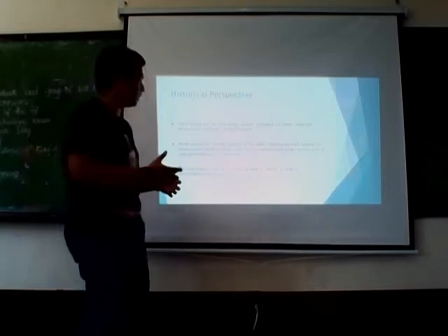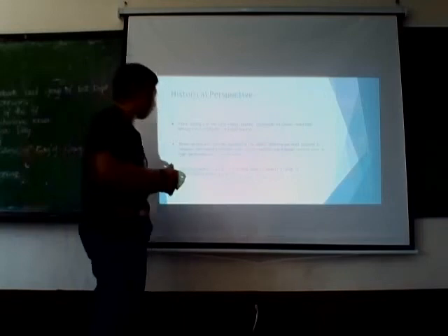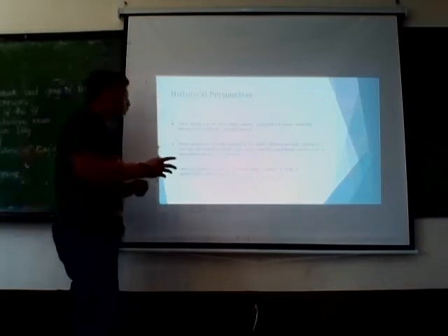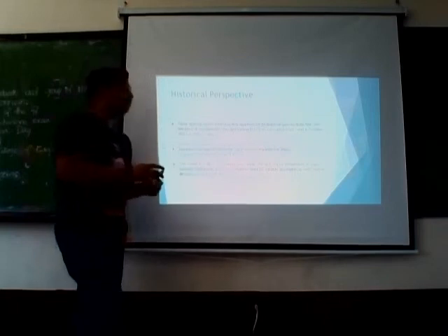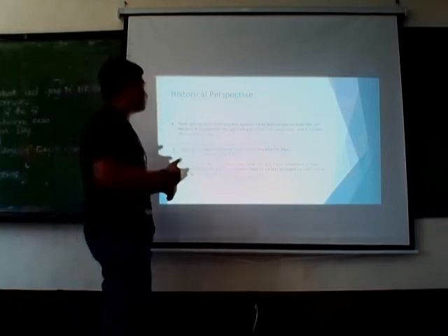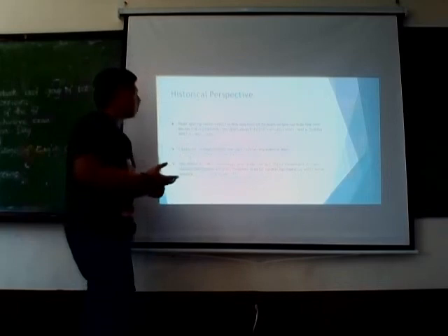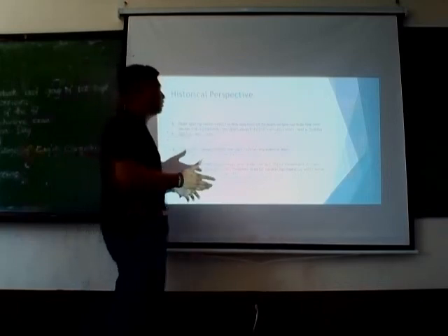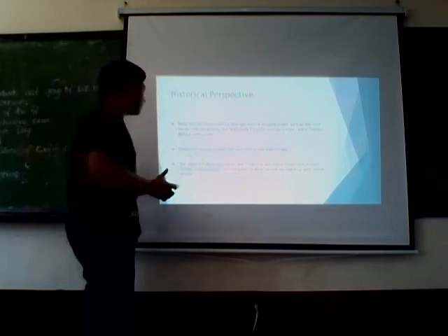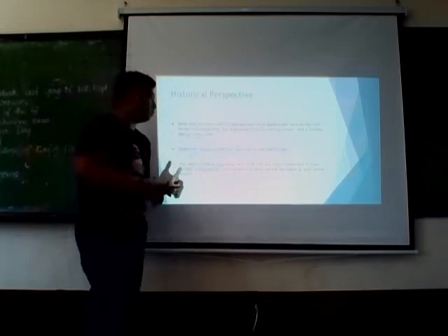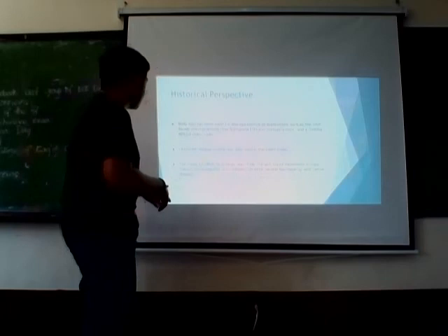Dynamic voltage scaling is commonly used to support a range of power and performance trade-offs. Body bias has been used for leakage control in applications such as the Intel XScale microprocessor, the Transmeta Efficeon microprocessor, and the Toshiba MPEG-4 video codec. Clustered voltage scaling was also used in the video codec.